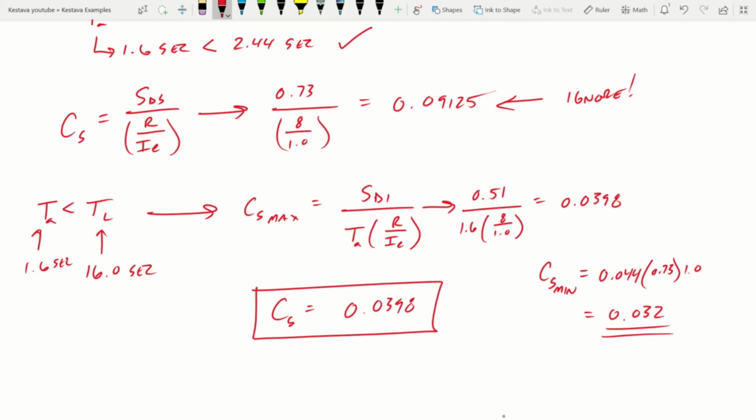I mean, you can see how low this number is. They provide it in the code, obviously, but this shouldn't happen, really. I guess in seismic regions that aren't controlling really that much, you still have to check for it based on maybe a special type of building. Maybe that's where it comes in handy, but this almost never controls, ever. So just my word of wisdom there.